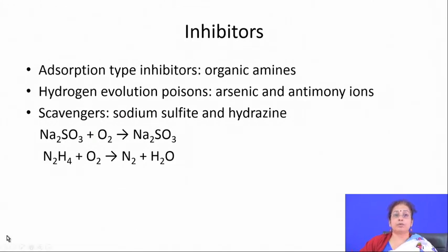If you talk about altering the environment, as I mentioned, you can reduce the temperature, you can reduce the velocity, but sometimes these are not under your hand. You cannot really play with them, because those are natural things and where you have to use your component. So, in that case you can apply inhibitors to reduce the aggressiveness of the media, the aggressiveness of the particular environment.